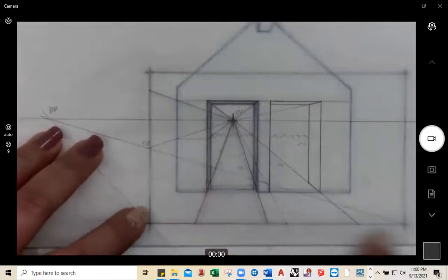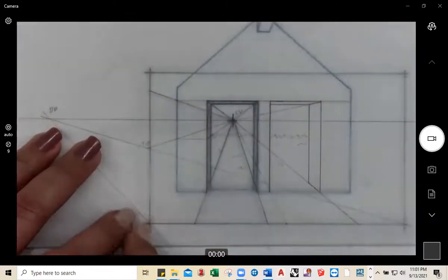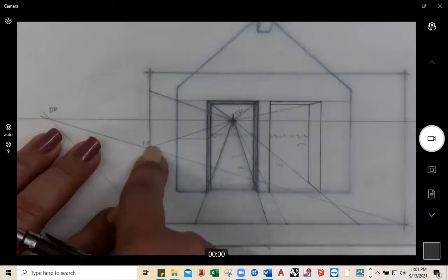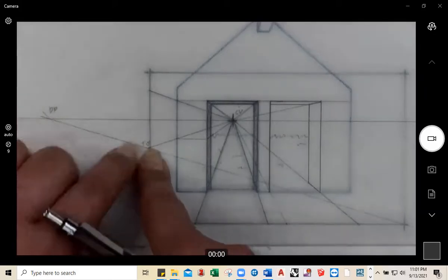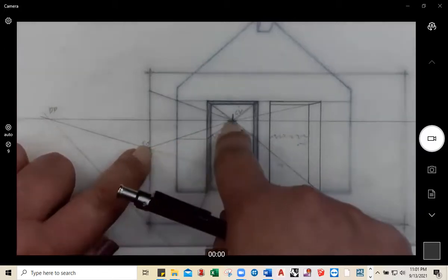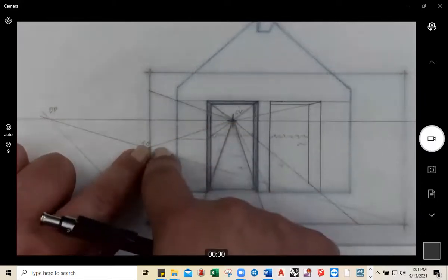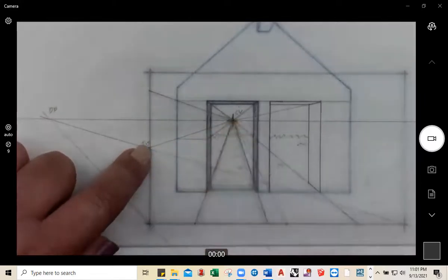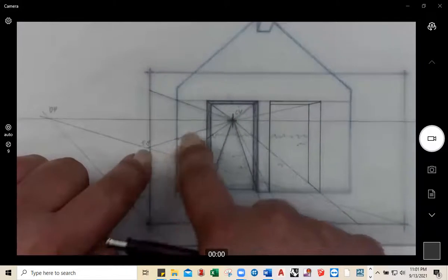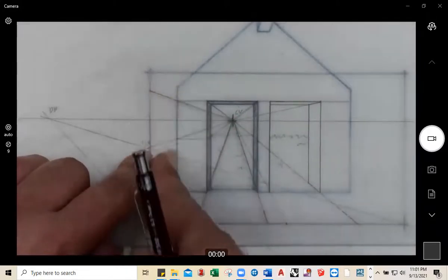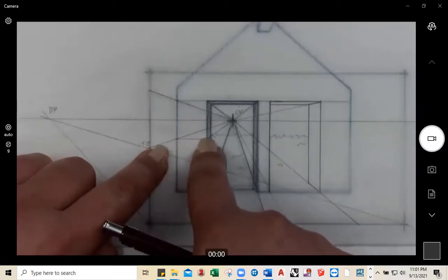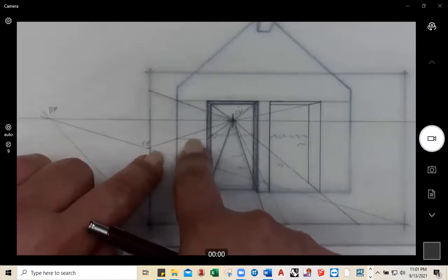Well, on our picture plane, over here, notice on the left-hand side, I measured 4 feet. At 3/8 of an inch scale, I put a little tick mark there. Then I drafted a line from that point to the center of vision. And similar to how we got the height for the portals here, where that diagonal intersects the back wall, right here, we're going to draft up a horizontal line because that's the 4-foot mark at this back wall.